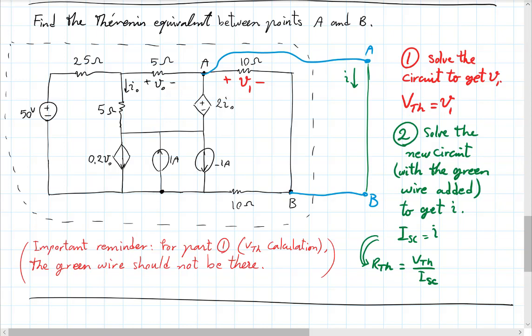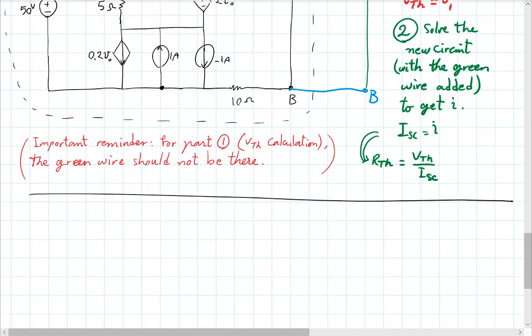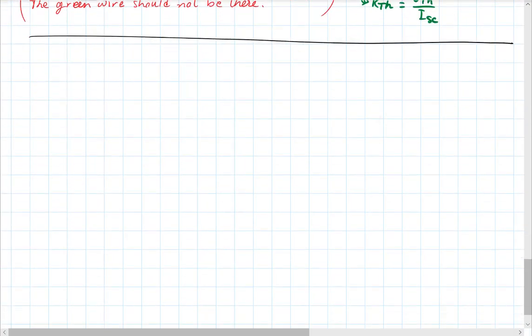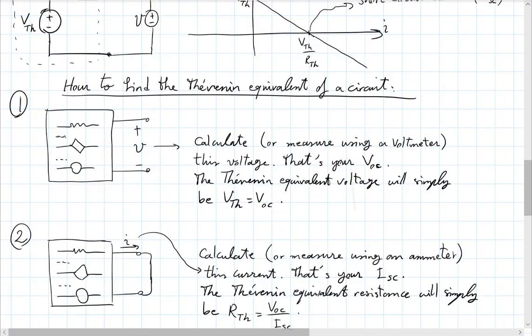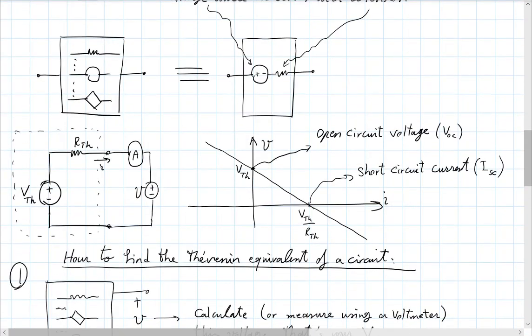Remove this to avoid confusion for a moment. So this is the Thevenin equivalent. And again, remember that it's a property of linear circuits. Now, I want to ask you guys to do a quick exercise. Again, try something on your own. Take these IV characteristics. This is all that matters for a Thevenin equivalent.